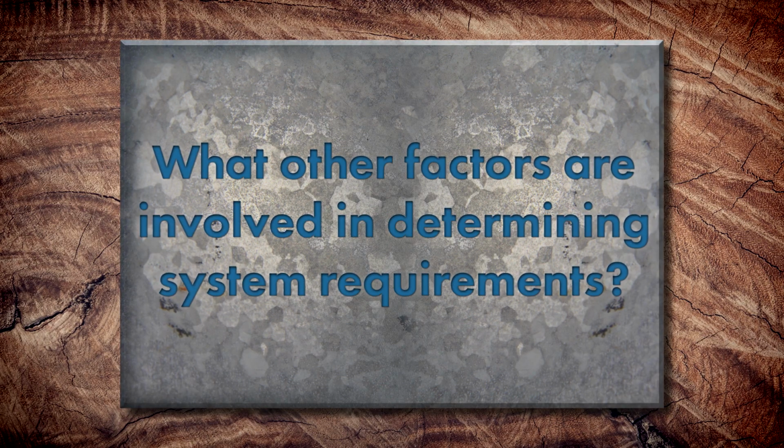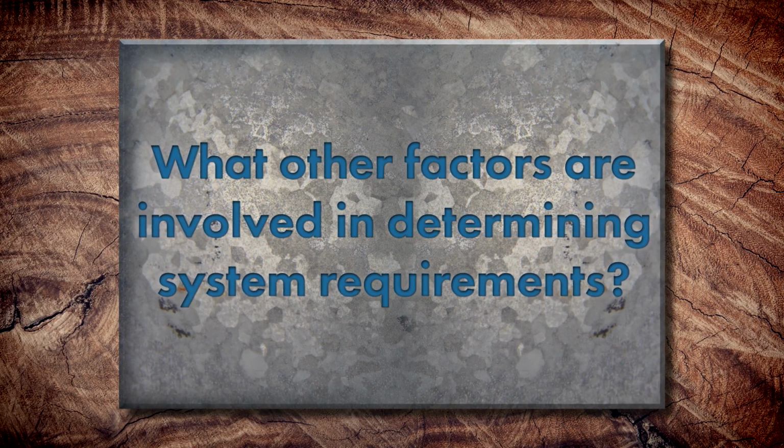So we have design pressures, we have exposure categories. What's next when we're considering design, location, stuff like that? Okay, so we talked about the design pressure and the panel you're going to use, the category that it's going to fall under. Things come into play as far as your roof mean height, so, the average height of your roof. Whether your building is partially enclosed or fully enclosed, because that affects how the wind's going to affect your project.